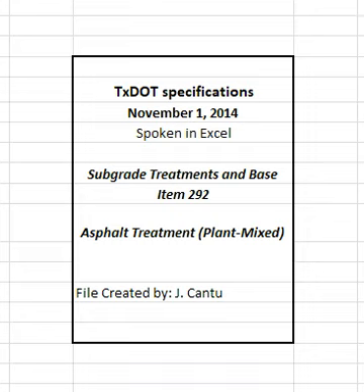4.2.2 Mixing and discharge of materials. Notify the engineer of the target discharge temperature and produce the mixture within 25 degrees Fahrenheit of the target. When ordinary compaction is used, the engineer will select a target discharge temperature between 225 degrees Fahrenheit and 350 degrees Fahrenheit. Produce the mixture within 25 degrees Fahrenheit of the target. Monitor the temperature of the material in the truck before shipping to ensure that it does not exceed 350 degrees Fahrenheit. The department will not pay for or allow placement of any mixture produced at more than 350 degrees Fahrenheit.